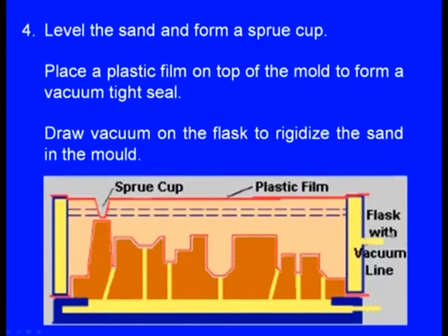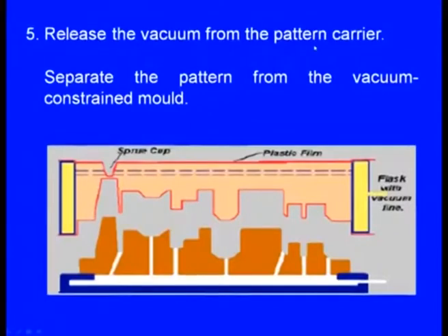Once we apply the vacuum here, what will happen? The sand will be held rigidly. So, that is the purpose of this second vacuum. Next one, release the vacuum from the pattern carrier.